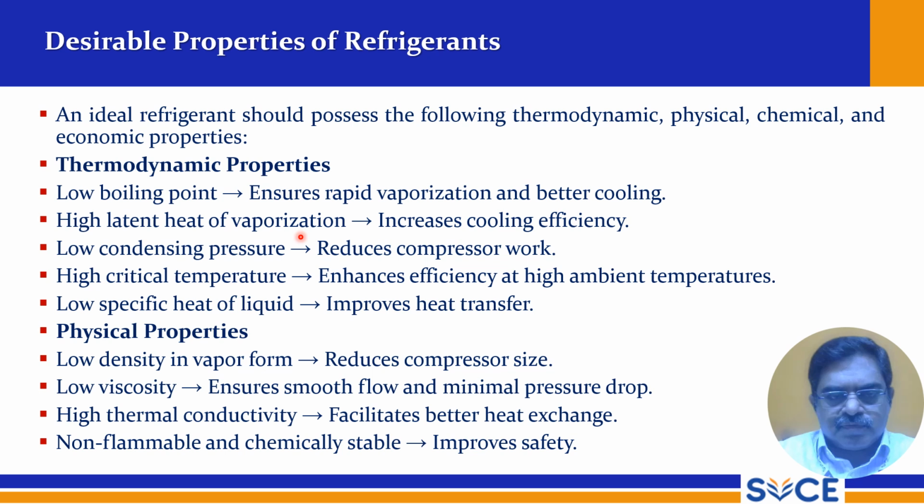High latent heat of vaporization increases cooling efficiency. Low condensing pressure reduces the compressor work, and a high critical temperature enhances efficiency at high ambient temperatures. Low specific heat of liquid improves the heat transfer. So low specific heat always improves the heat transfer. These are the thermodynamic desirable properties. Normally, to achieve all this in real refrigerants is really a difficult task.